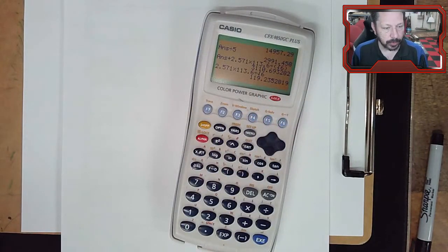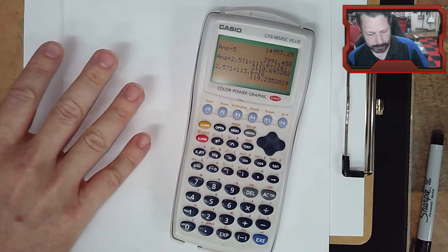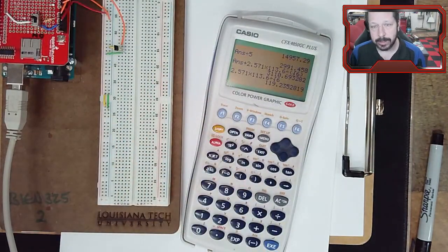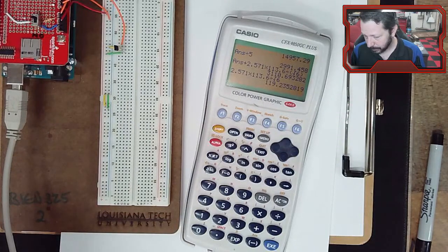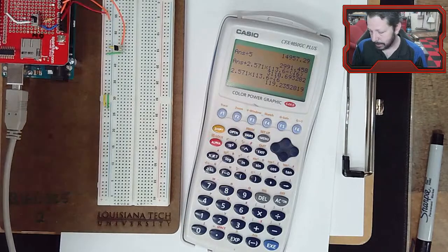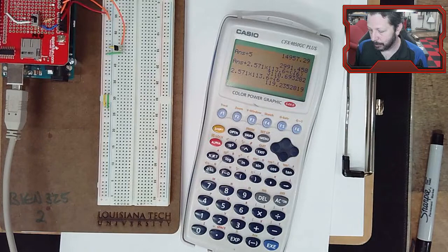Next time we're going to do some more uncertainty, and we're going to talk about all the things we've been sampling with our Arduino. With the Hall effect sensor or whatever, they've been pretty slow signals. But if I'm trying to detect something that's kind of fast, like a sound, with a quick pulse, then I have to be careful, because I can set up a microphone, capture the signal and analyze it, and get a completely different thing from what the actual signal is if my sampling rate's not correct.